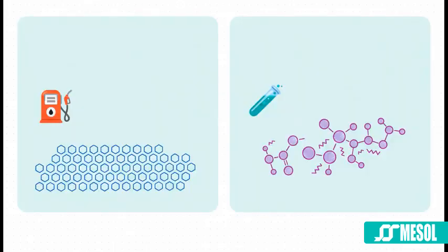But what if you're not just dealing with simple hydrocarbons? What happens if your system has things like alcohols or organic acids? These chemicals are what we call highly non-ideal. Their molecules have these strong polar attractions that an equation of state like Peng-Robinson, which was designed for non-polar stuff, just can't capture accurately. So to model these complex interactions, you must switch to a completely different tool called an activity model if you want to get results you can trust.